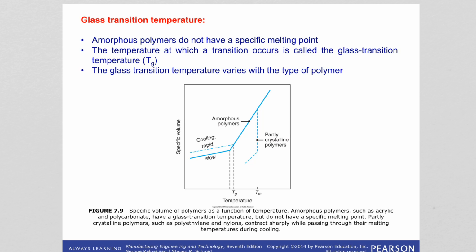So the glass transition temperature Tg, shown in the figure. If we start with, in this case, the specific volume is shown. It is decreasing with decreasing temperature, sharply decreasing, and then a more shallow decrease here, because we are going to a more glassy region. So below the glass transition, the material will behave glassy. Okay, that means they are becoming more brittle.